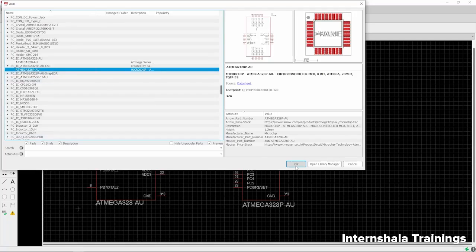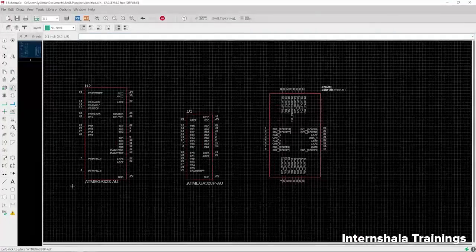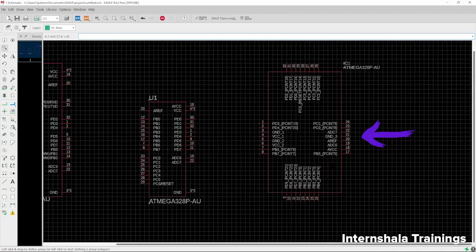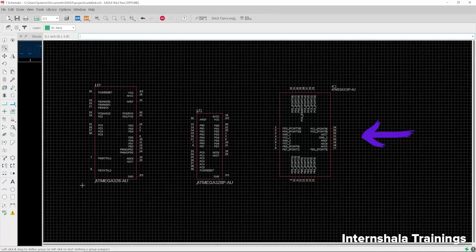just a second, let me click on OK. So this is how the symbol from the Component Search Engine website looks like. And this symbol is not good at all, and I would not recommend you to use this kind of symbol when you design a circuit. There are some standards that you need to follow while you create the symbol. There is one standard which is called the IPC standard.